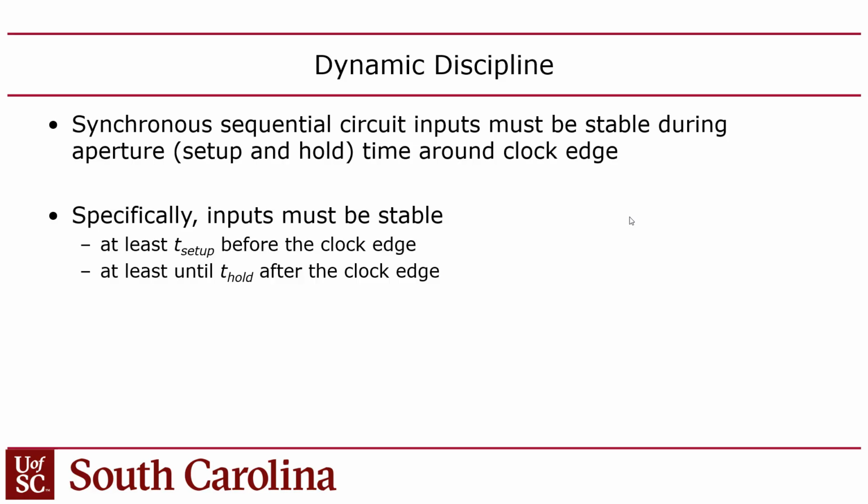But you may have to worry about it if your SystemVerilog is trying to do too much inside of one clock cycle, right? In which case you may not be able to meet timing. The CAD tool may not be able to help you. In other words, when I say the CAD tool, I'm talking about the compiler, the synthesizer, right?